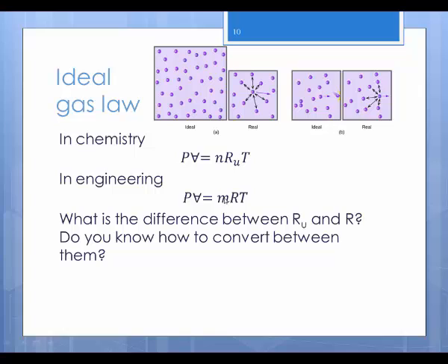And that's probably, if you think about it, going to be different because 5 kilograms of neon is not the same amount of moles as 5 kilograms of nitrogen. And if you go back to this chemistry, well, the moles aren't the same, so why would any of the other solutions be the same? The moles is the more fundamental idea in the ideal gas law than mass, but making it where we have a substance-specific R makes it a lot easier to use this.